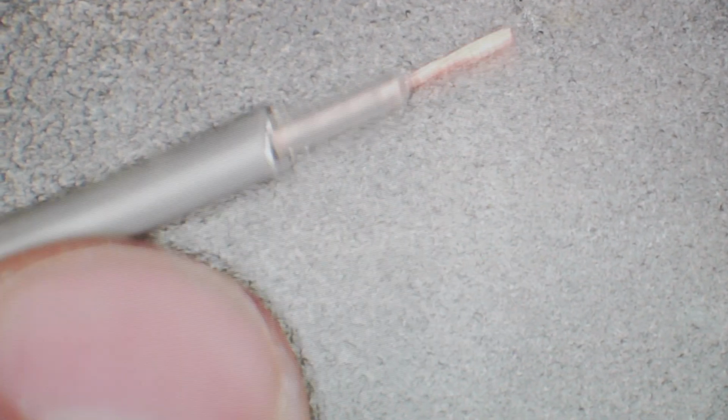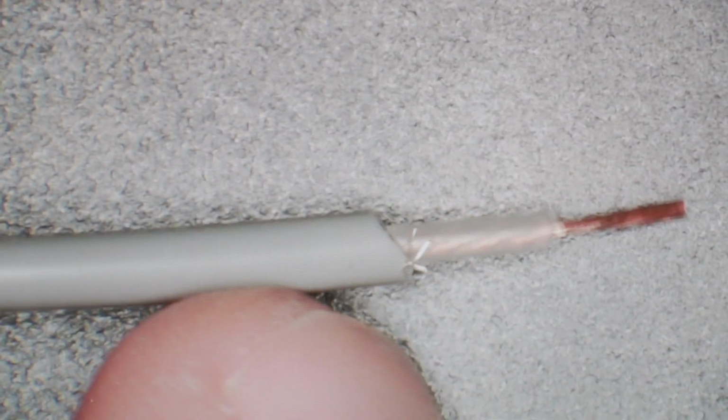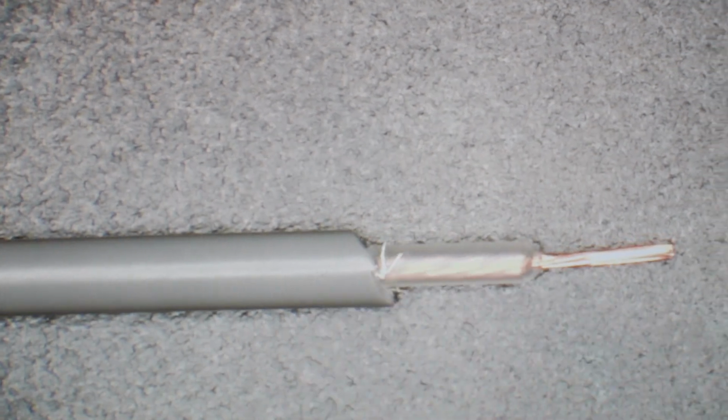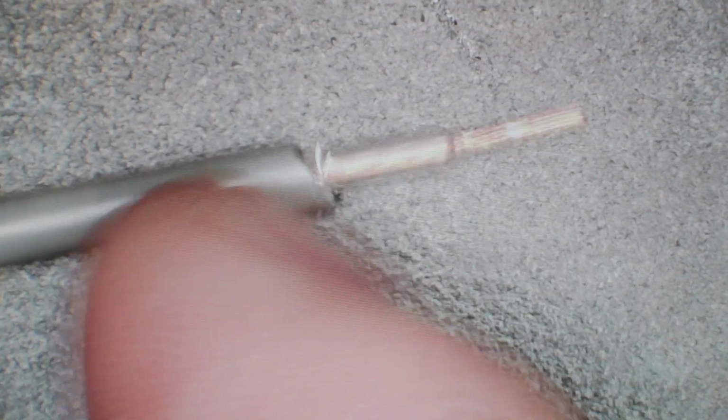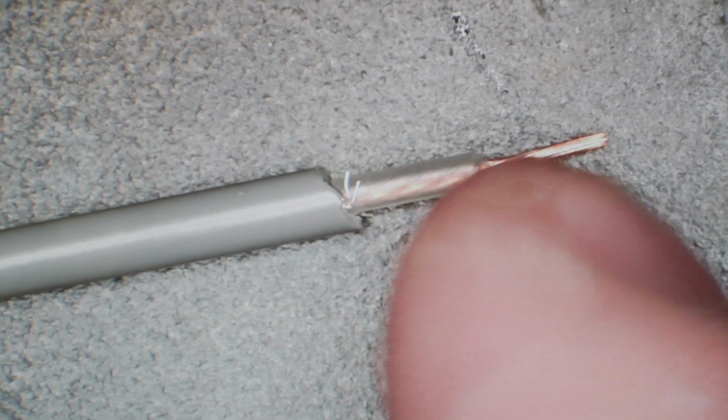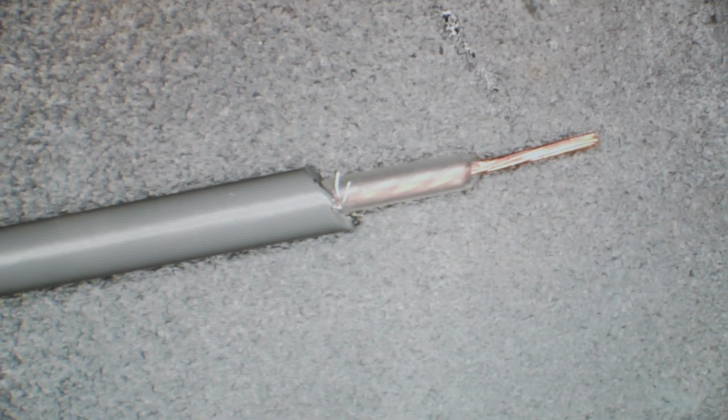And this is a cable that's already been pre-done. We've cut it back. We've ensured that no antenna portion is anywhere near the signal, because that will cause noise or interference. That's what happened in the first part of our project. This shielding was not trimmed back like it is here, and we had some signal problems. So this step's super important.